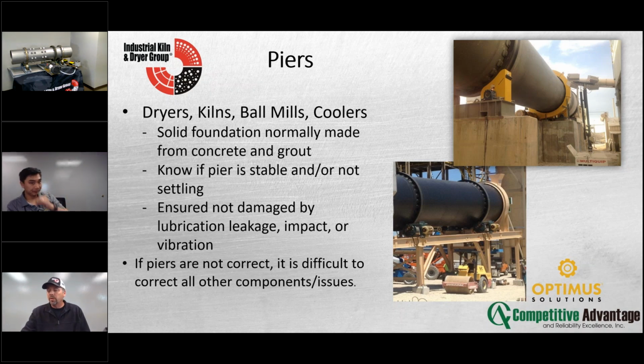Yeah, and a lot of times, even with concrete piers, you'll see items grouted in. So you have the base, the grout under the base, then the concrete pier under it, and then the foundation under that. Some of the foundations have gravel or something that's unstable. I don't know if you've seen this a lot, but you see some lubrication that's leaked. Oh, all the time. And also, to your point about the different styles, you'll see that with the heavier units, as you mentioned, going with the concrete piers.